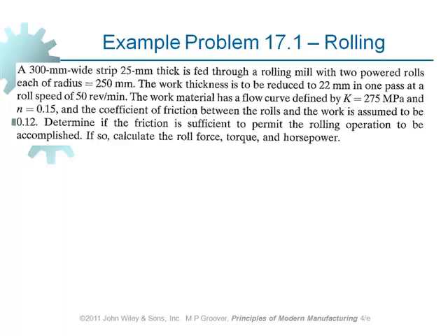So when it's hot working, n is always equal to 0. When it is cold working, it has got a non-zero value. So if we are provided with a hot working operation and n is not given, it's very obvious that n is 0. If it has got a value, it means that material is getting harder and harder, so it is below recrystallization temperature. Okay?